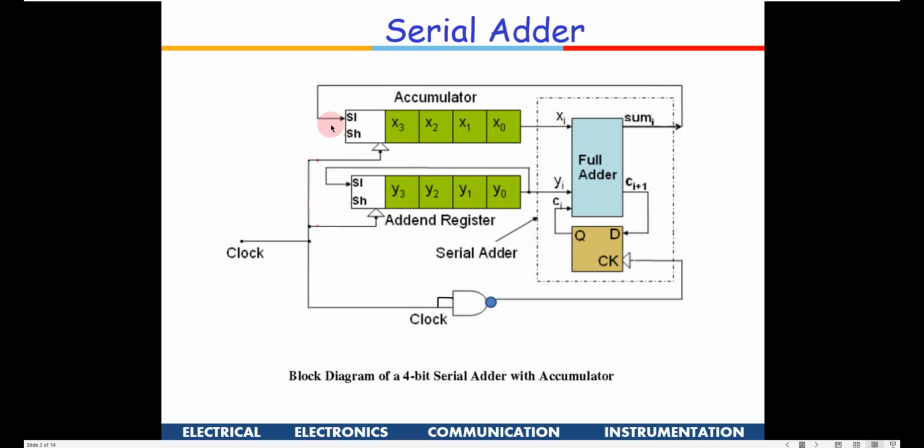So if you want to get the carry also here, finally you have to do another shift operation to get this. You put the carry here and you give a 0 here. Okay, so that also can be done. Now if you see here, the hardware requirement is pretty low, right.